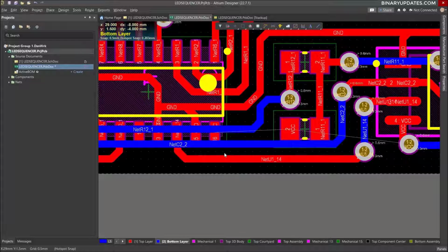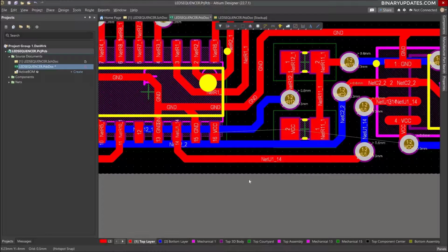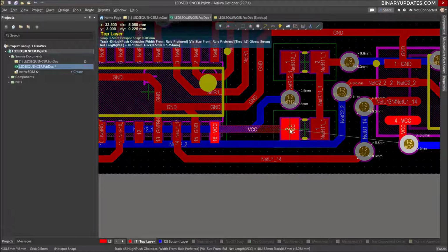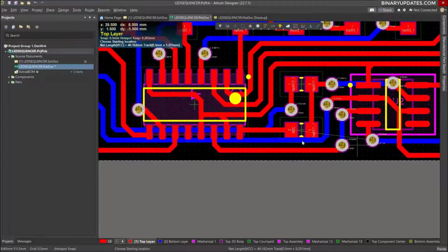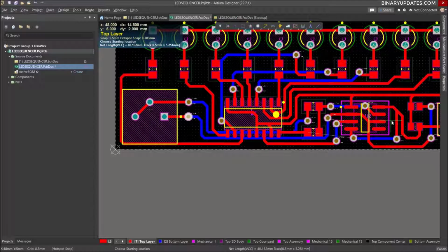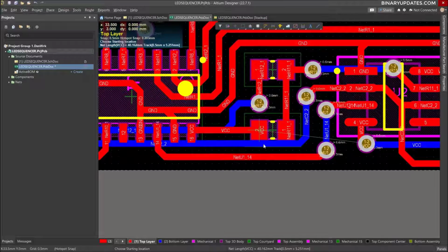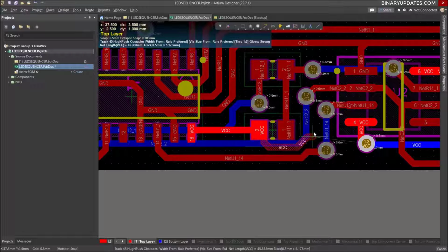Okay, that's the track 1 with the VCC, but I think this is pretty straightforward. I think if I go to top layer, Control W, this connection will be straightforward. Yeah, it's done. Now one connection left, which shows to this vias, right? So this resistor has to connect to this one. And let me try and see if I can draw this track here.